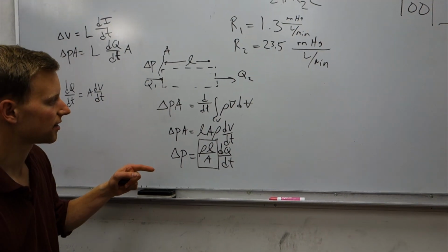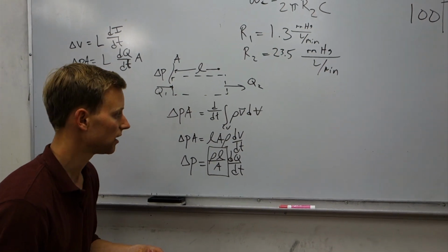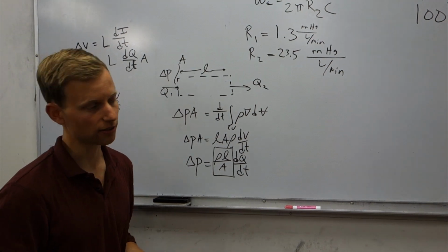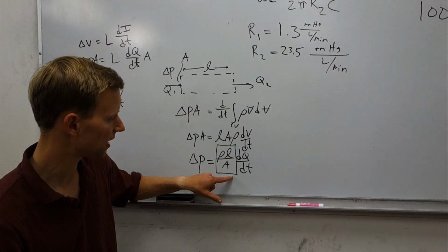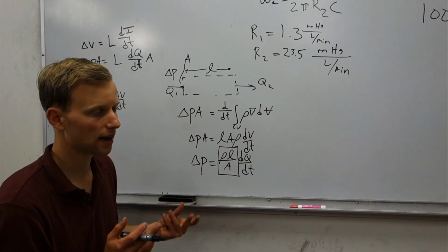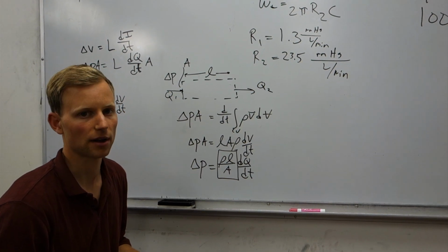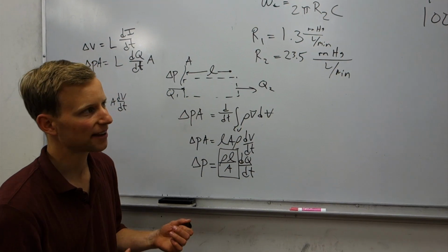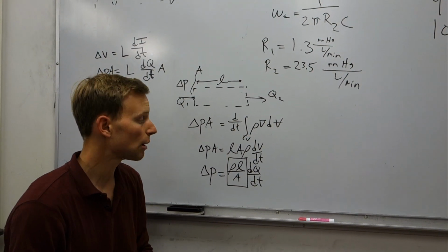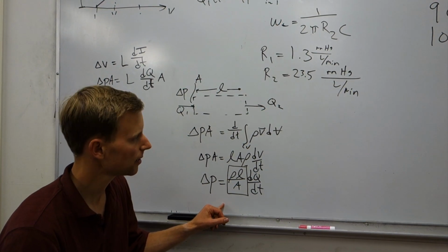And we could have modeled this in our system. We wouldn't have actually had to build anything extra in our fluidic circuit because the inductance is inherent. We can't get rid of it. It's the inertia of the fluid. But we could have included it in our modeled electrical circuit as either a parallel or a series inductor, depending on how we wanted to have the model happen. And in fact, the Windkessel model does include flow inductance, but we have neglected it. So that would be one thing we could add to make this model predict the pressure better.